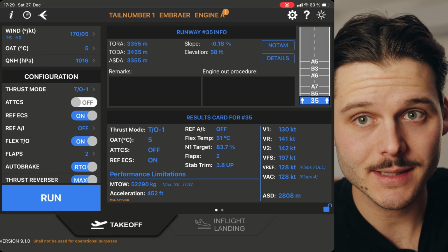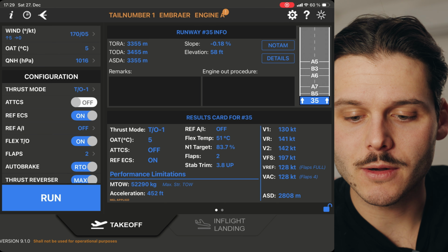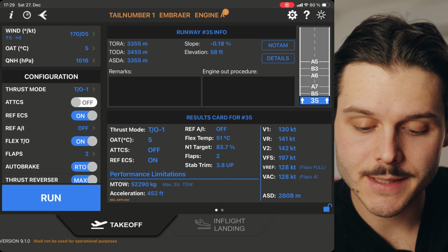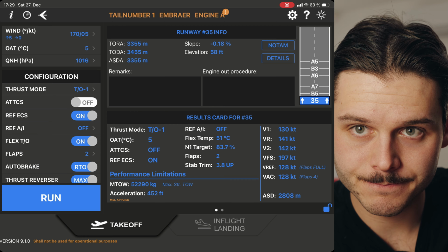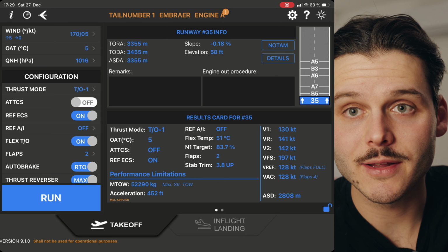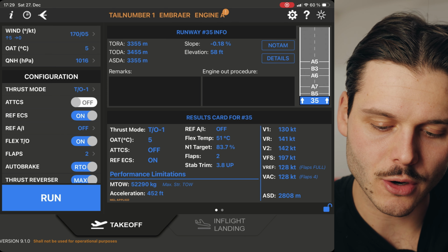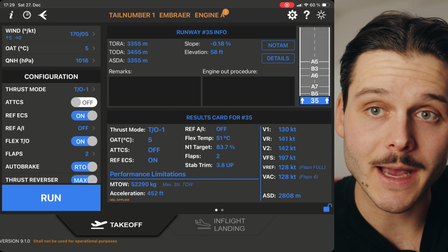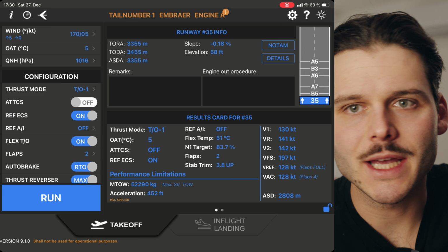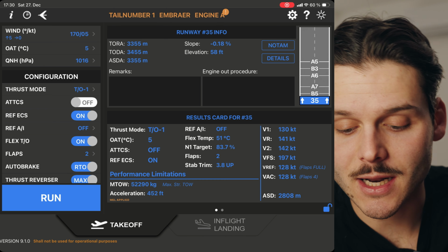This is something I've talked to many pilots across my company about, and I don't really get why that is, but it's the same with our ePerf calculation program as well. You see here in the top results card for the V1 speed, you have 130. Down below is VR, which is 140. So let's say you have an engine fire at 135 knots, which is above your V1 speed, so you have to continue the takeoff roll. You have to take that engine fire, go up in the air, do a holding pattern, do your checklist work, be back on the ground, let's say in 10 minutes. Let's say your engine is still burning, so you have a really big issue here, a really big risk taking it up in the air.